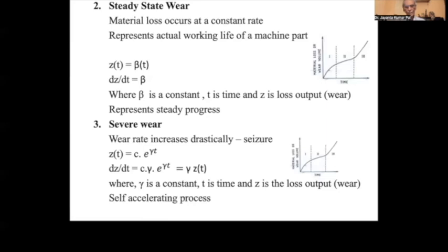So it wears out at a very high rate, and it can be seen here in this graph that the wear is in an accelerated manner. And here it is necessary to arrest the wear by some means or other, otherwise the component will be unusable. It is important to remember that in both these zones, the running in zone is a decelerating process, but at the end of the decelerating process again, this deceleration should be maintained.